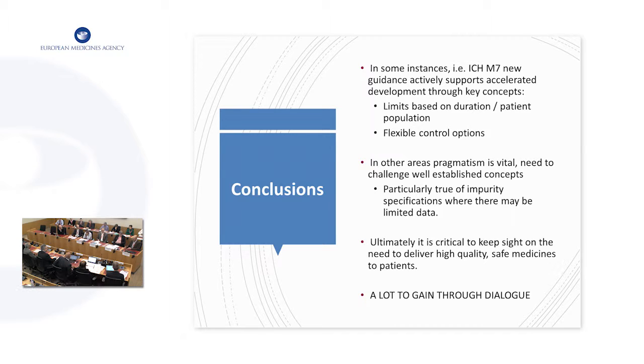And what we found, both in publications that I've been involved with directly, but in multiple other industry publications, is that when you compare the purge of an impurity to the predicted purge, there is a systematic bias associated with this, and it's a deliberate one, that it actually underpredicts. Example after example across all of the published literature on this, and internal anecdotal evidence as well, is that it underpredicts typically by about a factor of 10. Whatever you see as a predicted value, when you measure it, it'll be tenfold higher typically, sometimes more than that. Why is that, and what's the systematic bias?